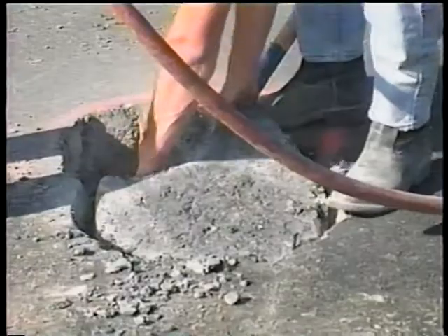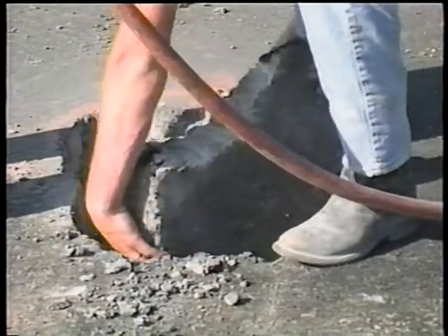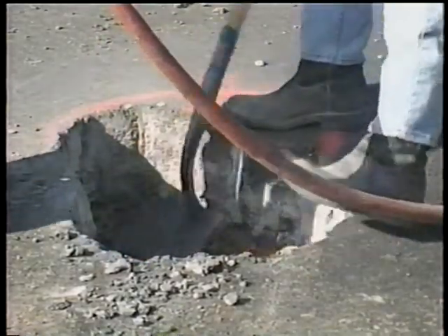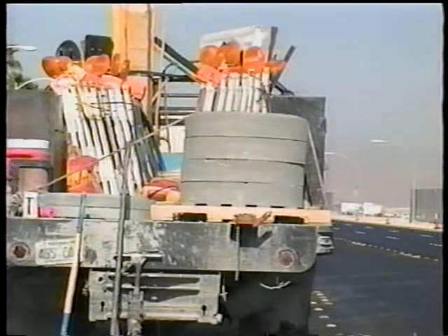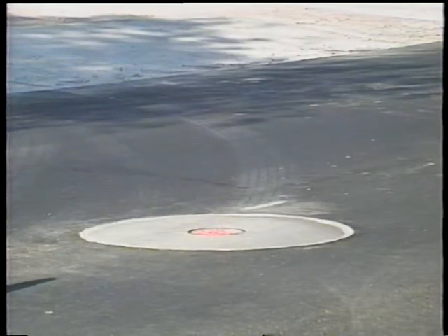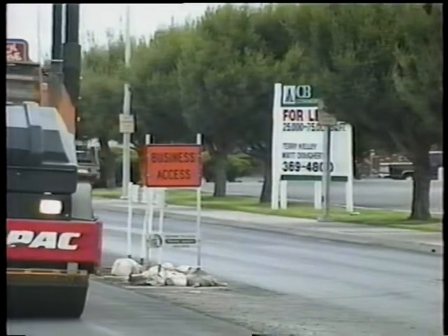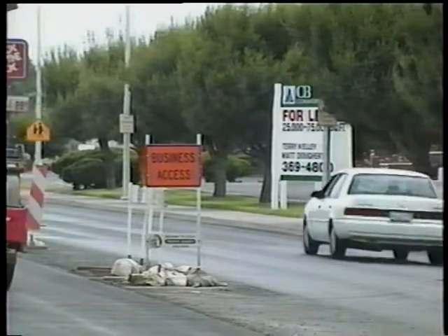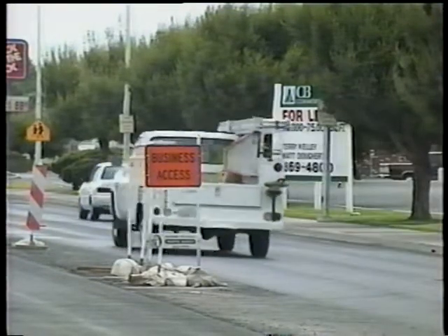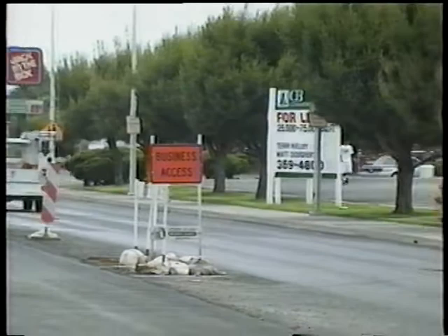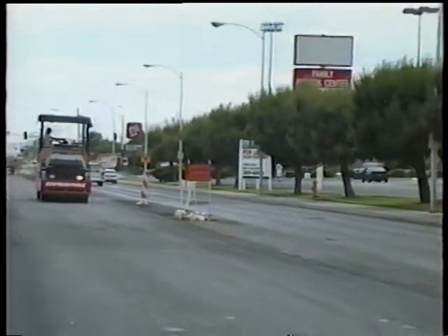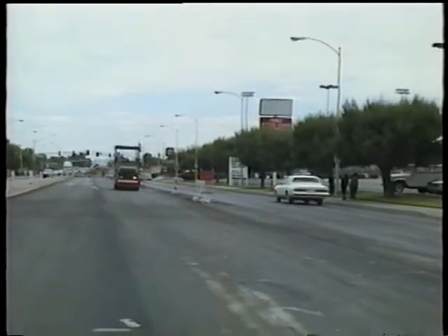As necessary, utilities may have to be notified early so that arrangements can be made to adjust manhole elevations. Also, any planned crossroad utility cuts must of course be completed and patched before the new pavement is placed. Businesses should be contacted to arrange access times for employees if entrances and exits will be blocked by the paving operation. Private residents must be notified too. As the inspector, you should check out all such arrangements before paving begins.